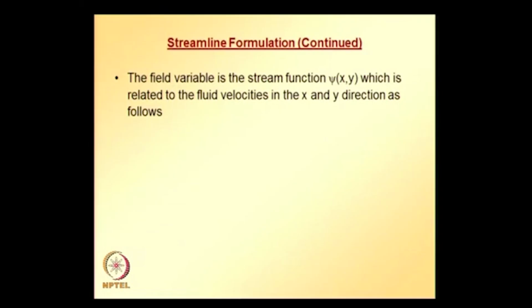So, the fluid velocities in x and y directions are related to the stream function psi, which is function of x and y, through these equations. Velocity in the x direction is the partial derivative of psi with respect to y. Fluid velocity in y direction is equal to minus of partial derivative of stream function with respect to x.